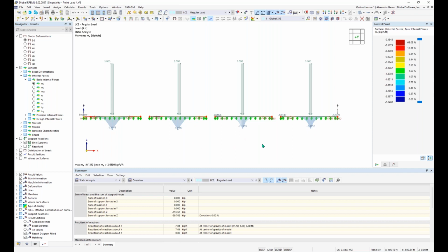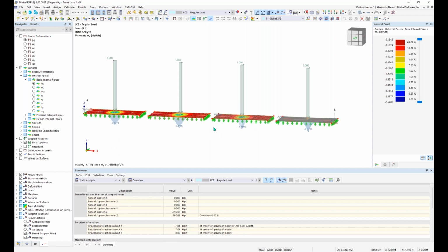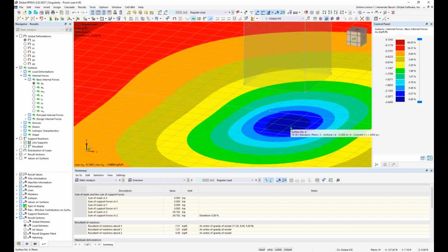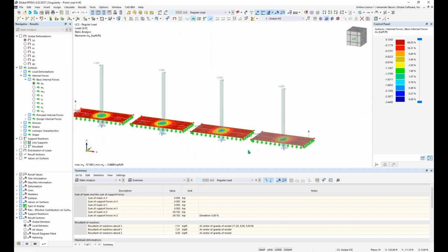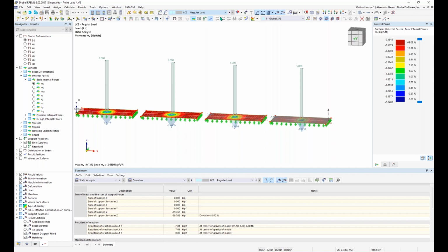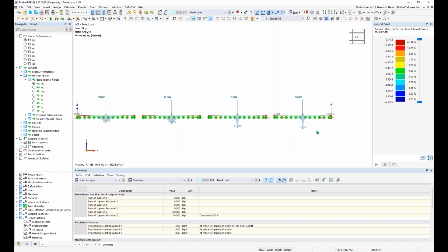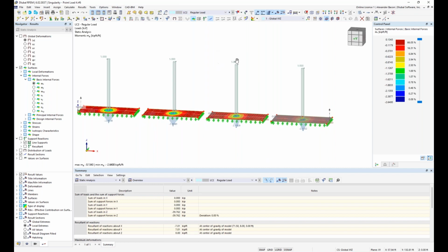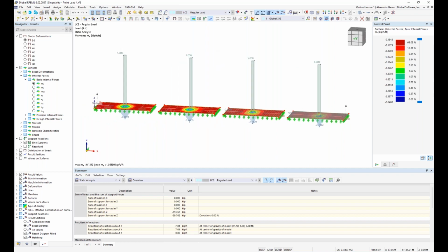And this is one way to fix singularities, is having the loading distributed over multiple FE mesh nodes instead of just feeding into one singular node. And we can compare this again to the singularity that we actually had in the first load case. So now, if this occurs, instead of doing this to fix the singularity, we could look at our result diagram for the section cut we have here.